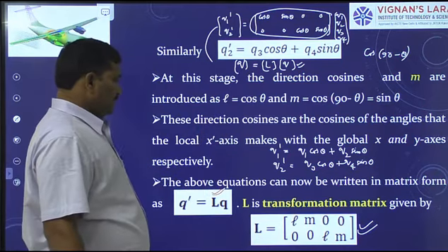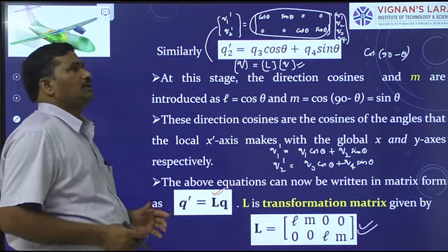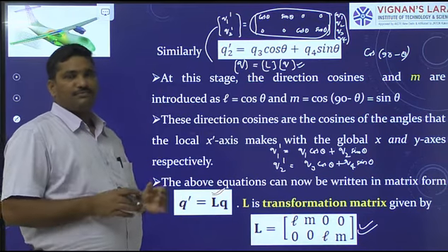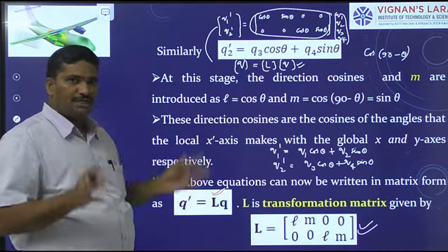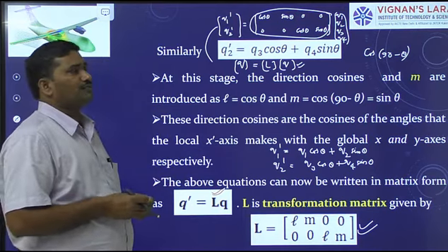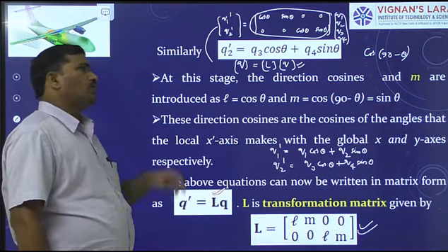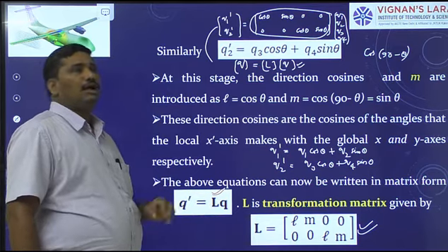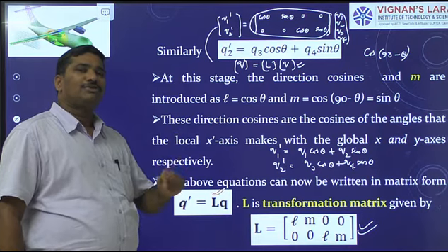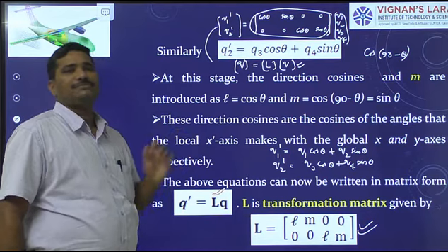So what we have learned in this particular class: we have taken a truss structure and understood how it behaves. A truss structure consists of several elements, each with a different orientation. Forces are applied at the joints, and under their action each truss member undergoes either compression or tension. No bending occurs.